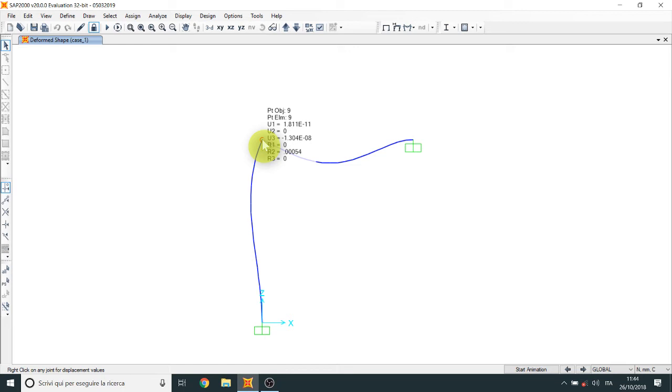If you are able to use the displacement method, you can validate the solution by using the displacement method. It's a really simple case because we have 4EI divided by L on the beam and the same on the column. With the displacement method you will have this situation. With the substructure 0 you will have this one.